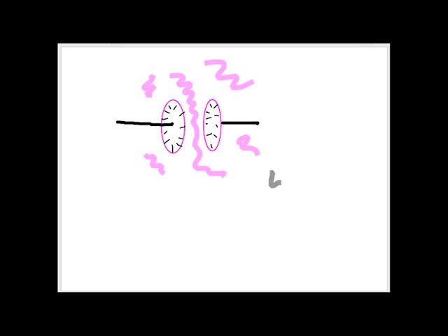So it's a type of limited slip differential. Because what happens is, if one side is moving quite happily, let's say for instance it's on a differential on the back wheels of a car. If one of the wheels lifts up off of the ground and just starts freewheeling round happily, then what happens is the other wheel goes stationary. That's how a normal differential would work.